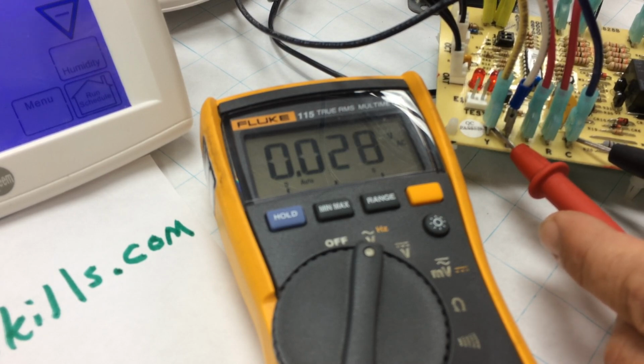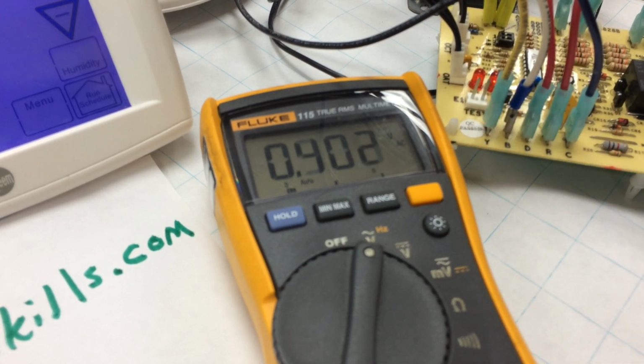Understand, whenever I'm checking voltage with a digital voltmeter, it's very sensitive. It can pick up some transient signals, and sometimes I'm checking for 24 volts and I may see 7.1 or 11.7 or whatever the case may be. Just understand what you have to make this thing work. Any low voltage control that calls for 24 volts has got to have between 19 and 30 volts. Don't spend your time chasing a partial voltage.